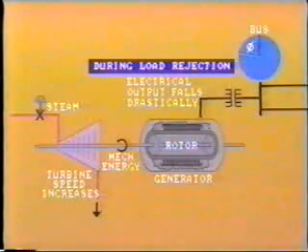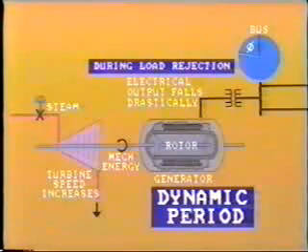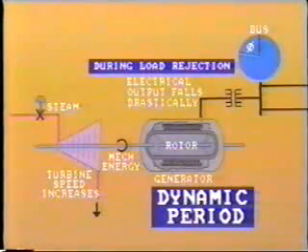This short period of time during imbalance, immediately following the disturbance and before a new steady-state condition is arrived at, is known as the dynamic period. The dynamic response during the first half second generally determines if the system will remain stable or not. You can see now why high-speed protection and removal of faults from the system is highly desirable.